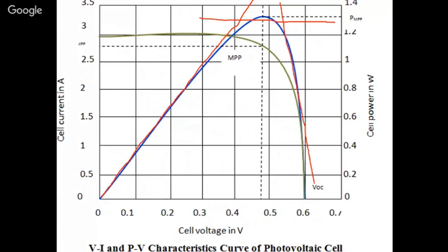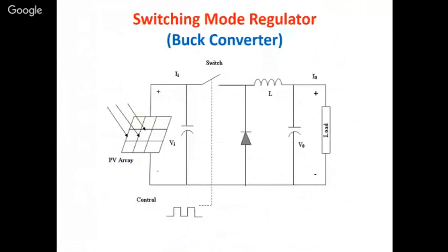Okay, so next, here this is the buck converter. Generally in the buck converter, the structure you can see here, you have a switch here, you have an inductance, you have a diode here, and this portion, usually in good books, they have this LC. So this is nothing but a low pass filter here. But in many of the books, this capacitor value will not be given. But in an actual circuit, when you get a real buck converter, you will have these two capacitors. Okay, this is a buck converter.